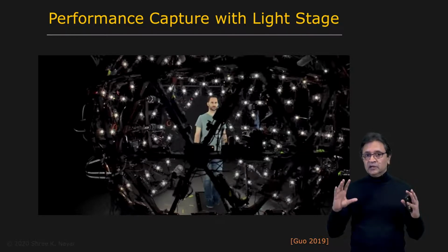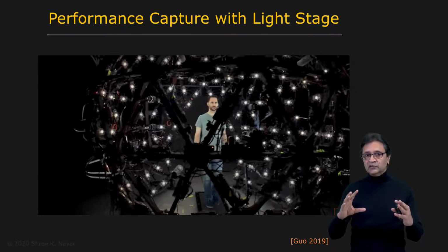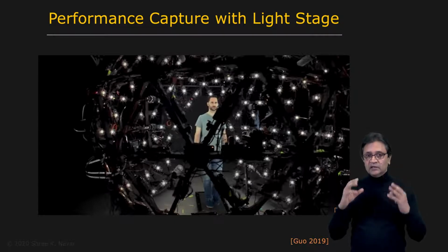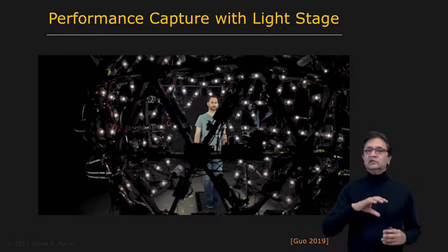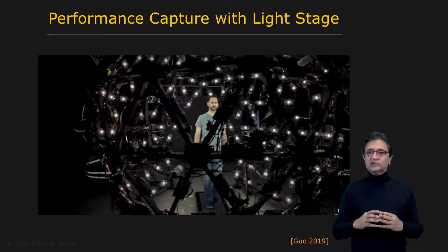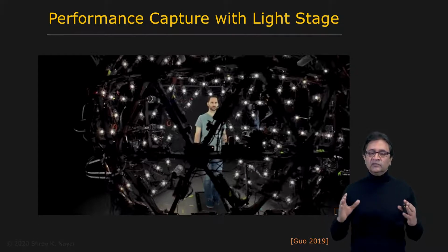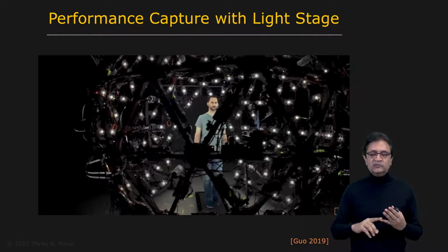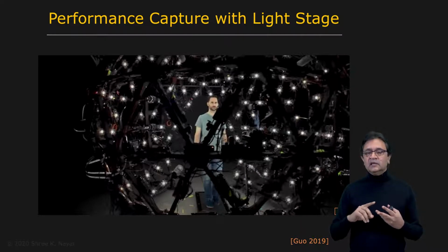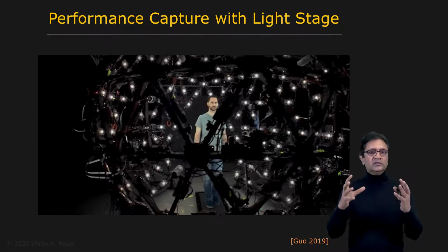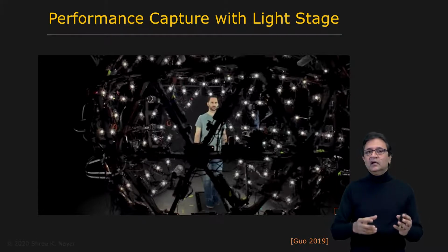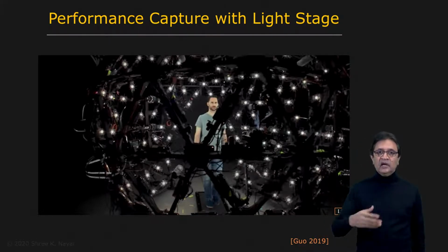It projects illumination patterns in the infrared domain so that you can get more detailed three-dimensional structure. And you're able to control the lighting and the camera system to capture enough information in a short duration of time so that you can actually get surface normal information, depth, the diffuse reflectance, as well as the specular reflectance. And once you have all of that information, you can then take whatever this object is that you're scanning and drop it into another environment and relight it.